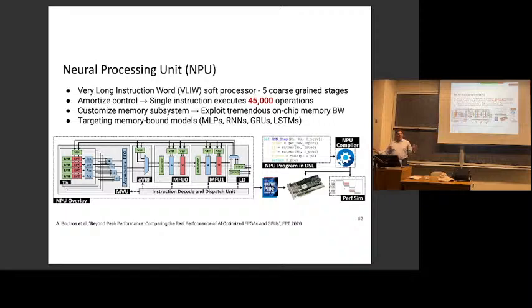They're controlling an operation on the whole vector of data. And the vectors are typically pretty big, 40, 80 elements, so it's quite wide SIMD. That's the second level of compute model they're using. So anyway, this is a vector register file, so it means you're accessing it. Let's say they made this NPU an 80 wide vector.